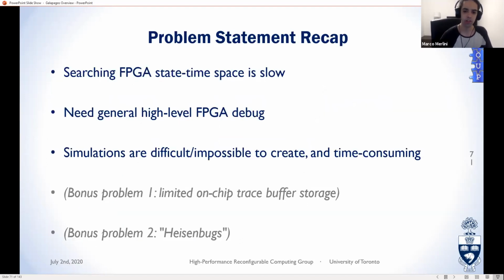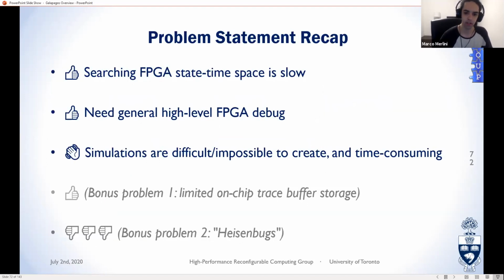So how did we do in addressing the problems we set out to fix? Since each debug governor is very lightweight, it's easy to have several dozen or even hundreds in your design. This significantly improves visibility while taking advantage of higher-level debugging. Our technique of replacing cores with a simulation can make it possible to run a faithful simulation, but only in the case that the much slower model doesn't affect the rest of the design.